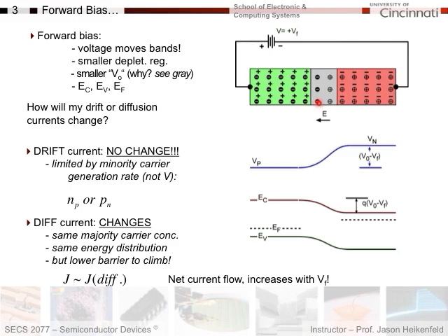That should make complete sense, because if you look at my contact potential, I've got negative voltage here, positive here. The applied voltage is opposite to that. Let's say the contact potential is 1 volt and we apply 0.5 volts here, then you would have 1 volt minus this for a net voltage drop of only 0.5 volts. This is in the opposite direction as this voltage, and therefore it gets subtracted from it. As you subtract that, you have less contact potential here, and if you have less contact potential, you must have less charged dopants here contributing to that contact potential.